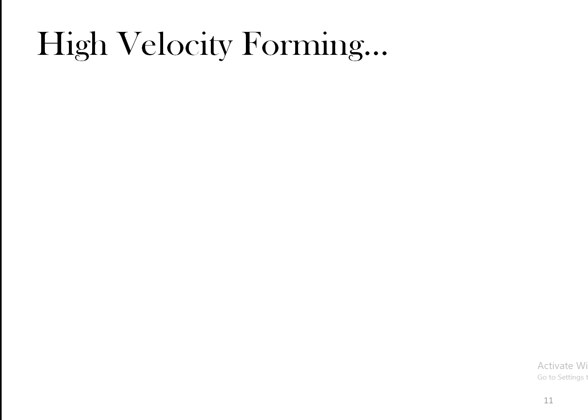The only difference is that it is actually a forming process, but it is subjected to a high velocity, or it is also called a high energy forming process. Okay. So the basic concept is that as the velocity increases, as you all know, your kinetic energy is given by the equation half m v square, half into mass into velocity square. Now as the velocity increases, the total energy with which the force is applied also increases to the power of 2, right? So as the velocity increases, the energy also increases.